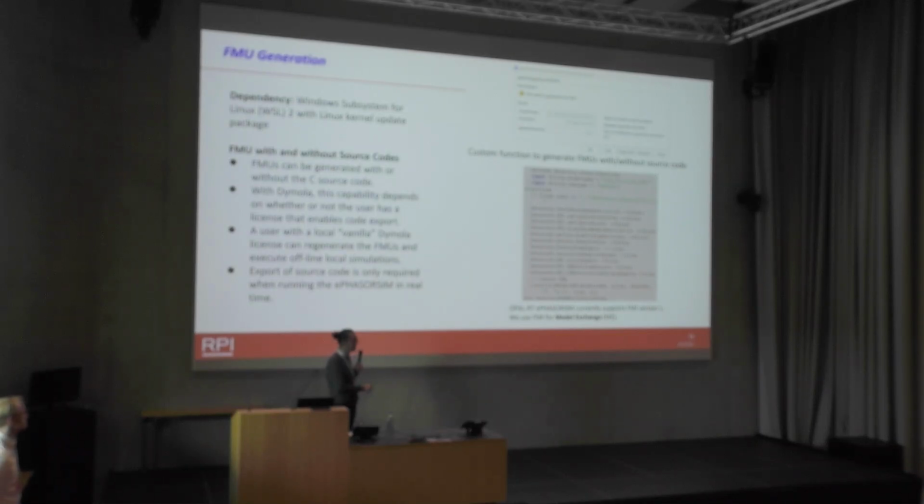The way that I found this is that I looked at the debugging logs of their little tool, called the FMU creator, and suddenly I saw that they have written all of these things, but you need all of this for the FMU to actually be able to run in their system. So it's another tricky thing, but once you set them up, you create a Modelica function that uses the code generation and so on.